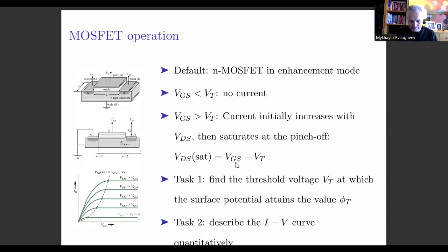So as you increase the drain voltage above the saturation value, pinch off happens, and the length of the inversion layer gets smaller as you increase the drain voltage, but not by a factor of 2, not by 10 times. It's just a small percentage, a small effect. The potential difference from one end of the inversion layer to the other remains fixed,